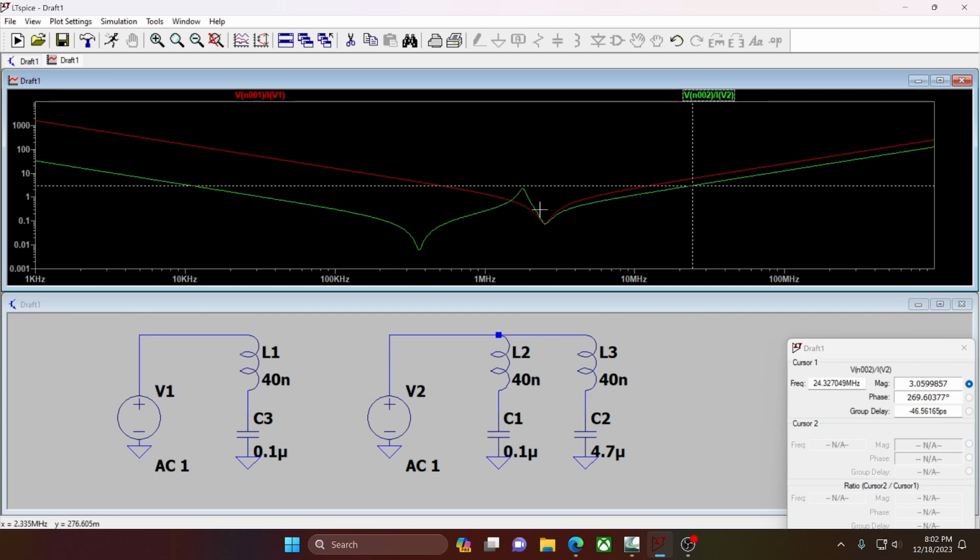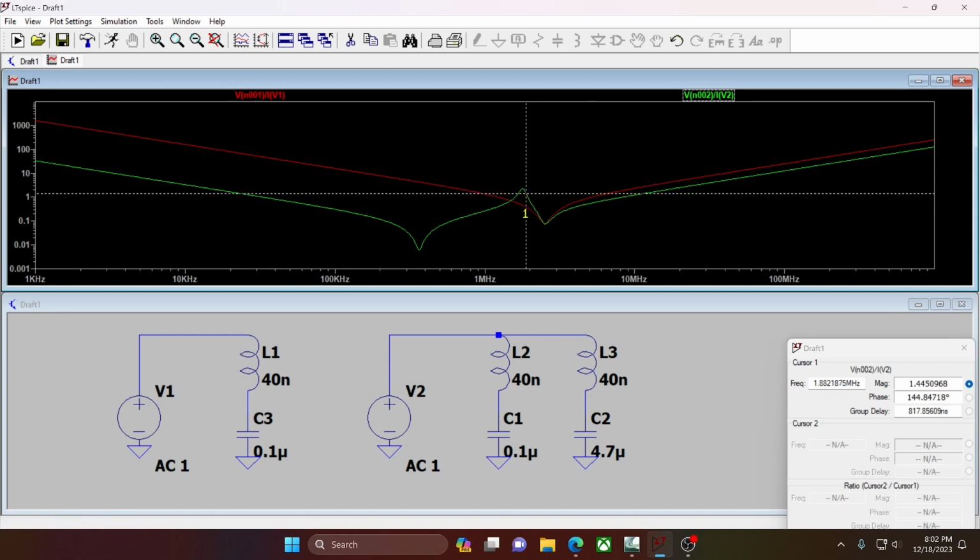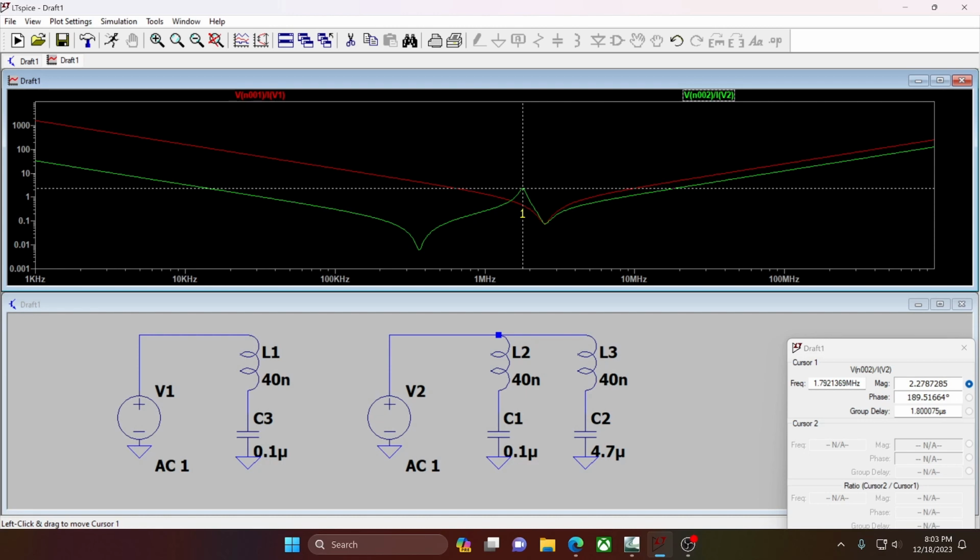But overall, if you deleted this from your mind, we're doing quite a bit better than just 0.1 all by itself, both in the low and the high frequencies. But if that peak gets too big, could be bad. Okay. So all in all, less inductance is better for the high end. Higher capacitance is better for the low frequencies.